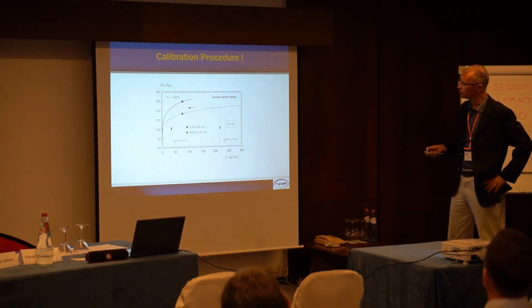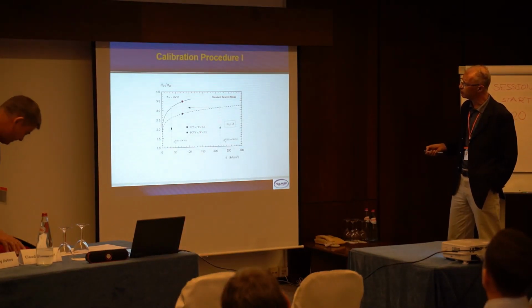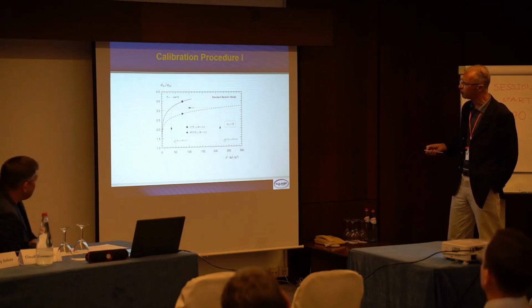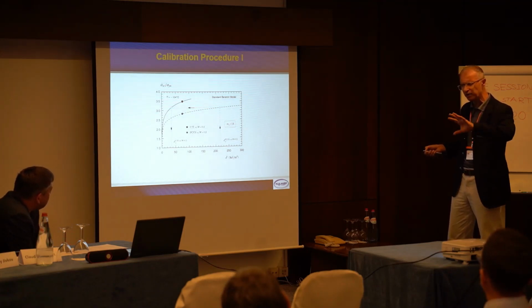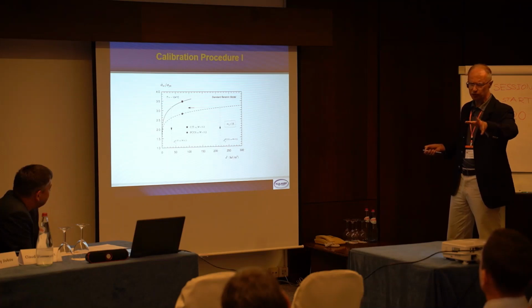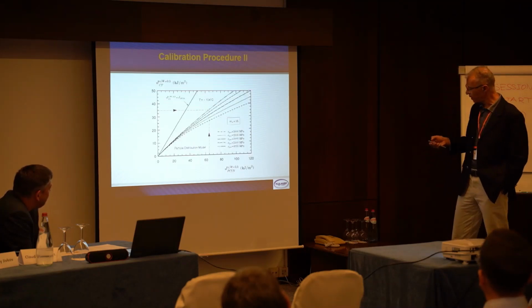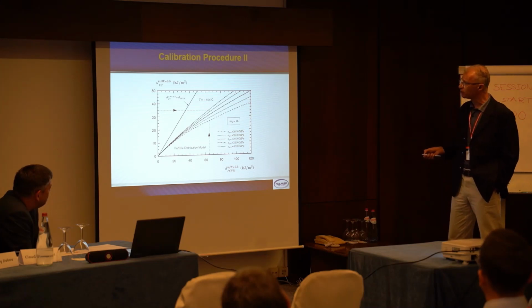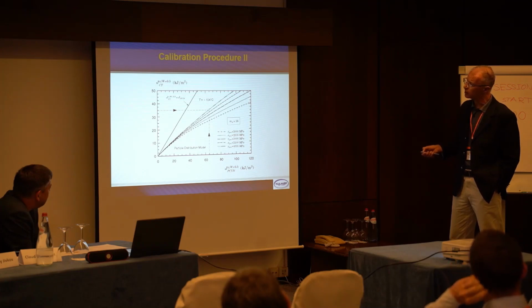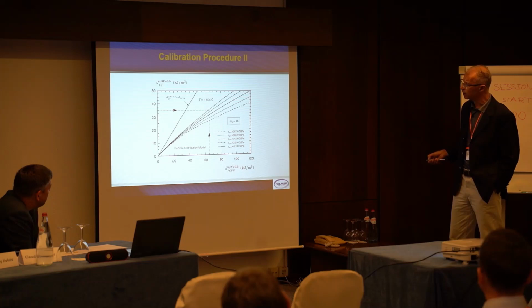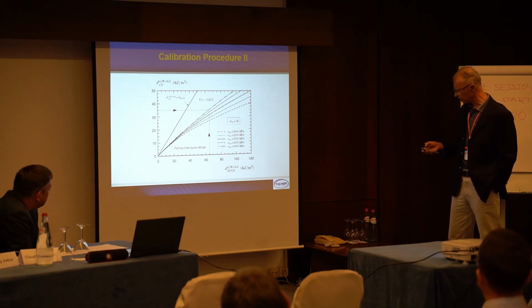For specimens with different geometries, in this case, the calibrated Weibull modulus is 16. It's actually very close to what's around for structural steels, between 10 and 20. That's a very good number. And we also ran the calibration for the particle fracture stress. Again, the same procedure, using the toughness scaling procedure from the CT to the pre-cracked Charpy with a/W of 0.5. And you can see here that it's close to 1,800, something like that.